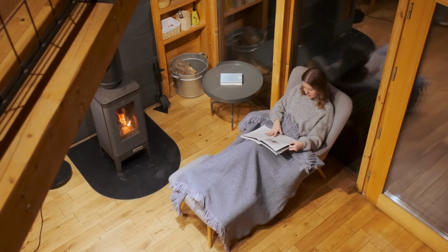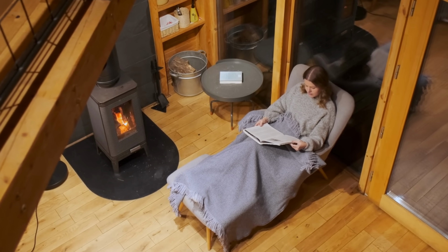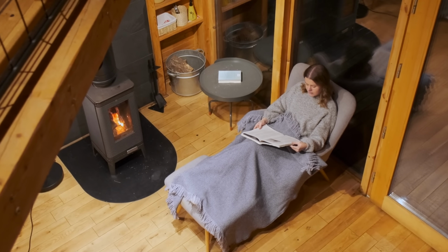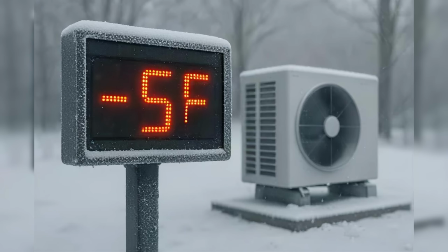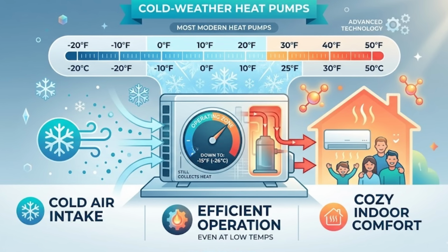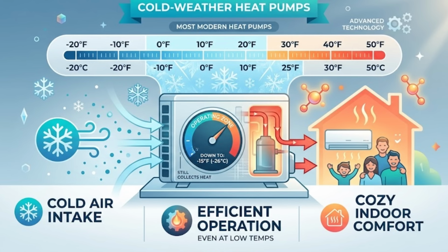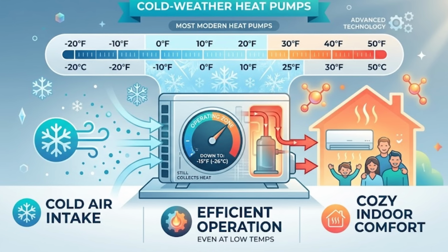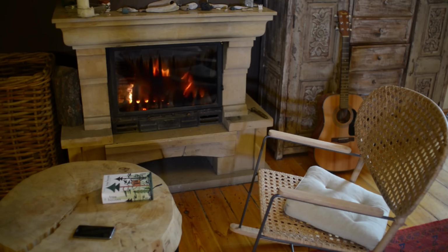If you have a heat pump, the contractor mode is even more critical because of the auxiliary heat lockout. Most heat pumps are programmed to turn on the expensive emergency electric heat strips if the outside temperature drops below 40 degrees. In reality, most modern heat pumps can still pull heat from the air down to 25 or 30 degrees. By lowering that lockout temperature in the hidden menu, you prevent the thermostat from turning on the toaster coils in your furnace, which can save you hundreds of dollars in a single cold snap.